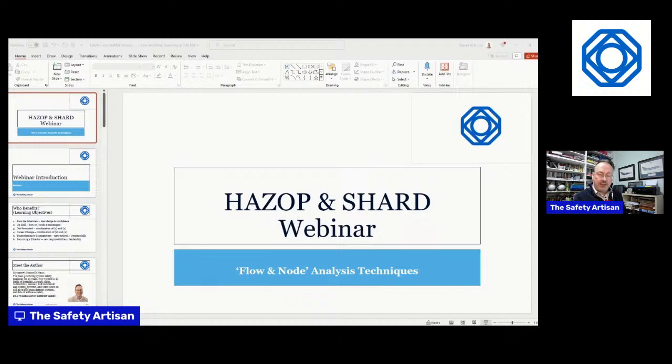Now the full HAZOP, it says, should be undertaken on a frozen P&I diagram. So it's frozen as in the design is frozen. So it's not going to see major change, because otherwise your HAZOP results become useless. And P&I is piping and instrumentation. So that's the terminology for a chemical plant. But as I say, we can use any kind of diagram where we've got stuff or information flowing between boxes or nodes. So we do the full thing with all the interconnections.